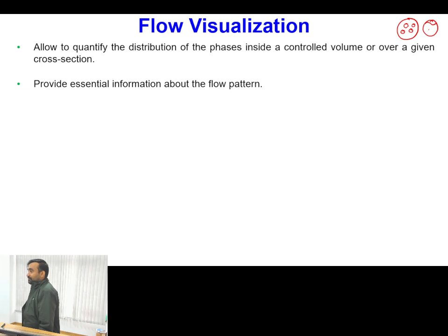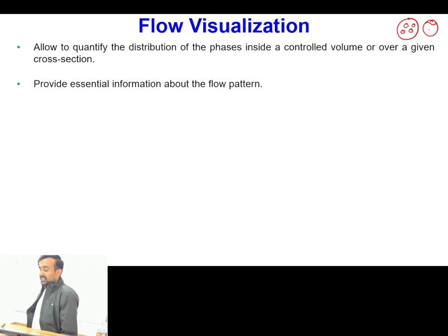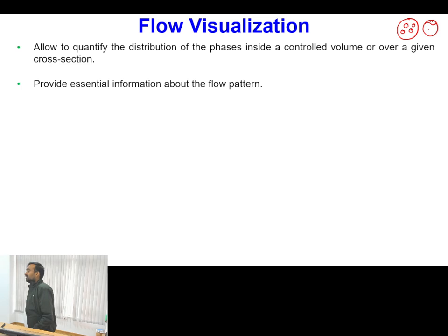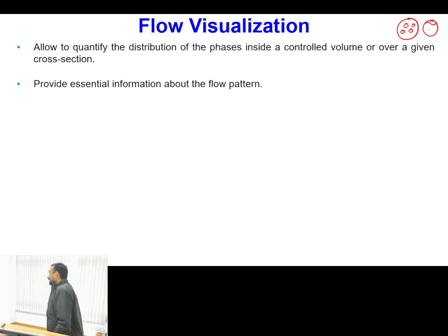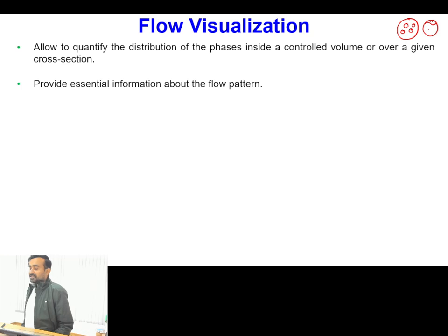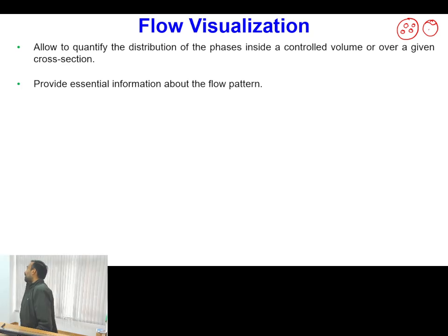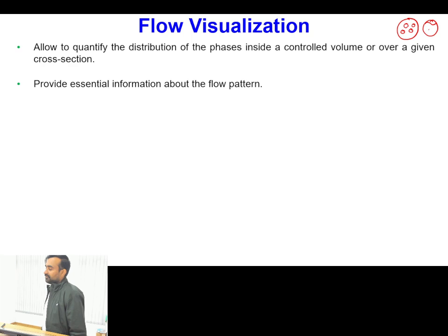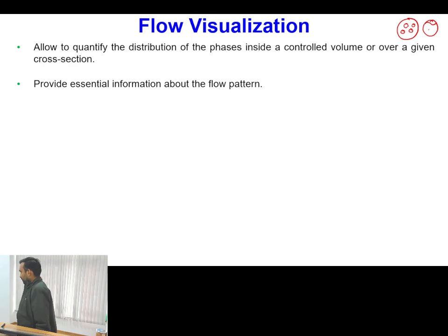But one important parameter will be different. In this type of situation, the interfacial area between the gas and liquid phase will be different for the two combinations. And in the case of multi-phase flow, the interfacial area between the gas and liquid is one of the important considerations in determining various mass, heat and momentum exchanges. Because if interfacial area is large, then we will have fast exchange of mass, momentum and energy, and if interfacial area is less, then the exchange of these quantities will be slow.